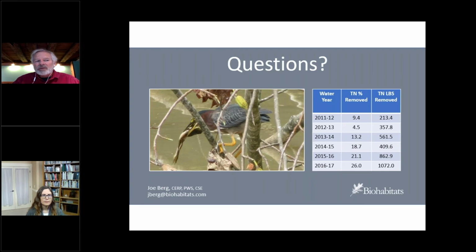In fact, one of our local counties is trying to get this kind of approach adopted as a stormwater retrofit BMP, just because not only does it get the improved water quality, but it lets the water out more slowly, so there's less downstream channel erosion. So that was part of their hook. Great, yeah, some volume control as well.